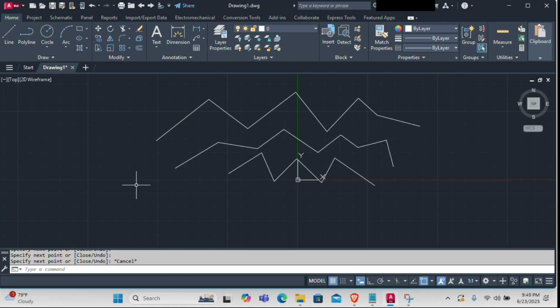But remember, when I taught you how to draw the line, I said these lines are individual. See, this line is individual, this line is individual, this line is individual. But polylines are not individual. They are a single connected line. Here when you select one end, all the lines are selected because it is a single connected line. So it is easier to move around. It can include variable width, and polyline also supports arc segments.